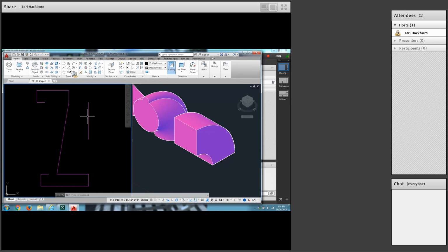Now, we need to make a special arc. It's up here at the top in my little draw panel. Click the little triangle, and you know that the start point and the end point are here and here. And we know the radius of the arc. It says it's 1 3/4. So right here, let's do start, end, radius. Make sure you're moving counterclockwise. So that means you would start here at the top and end here at the bottom. Be sure to drag your mouse until you see a curve. When you see that nice curve, you can type in the radius, 1.75.